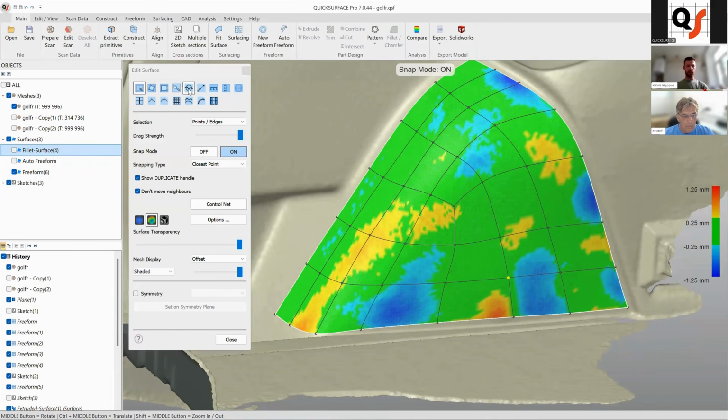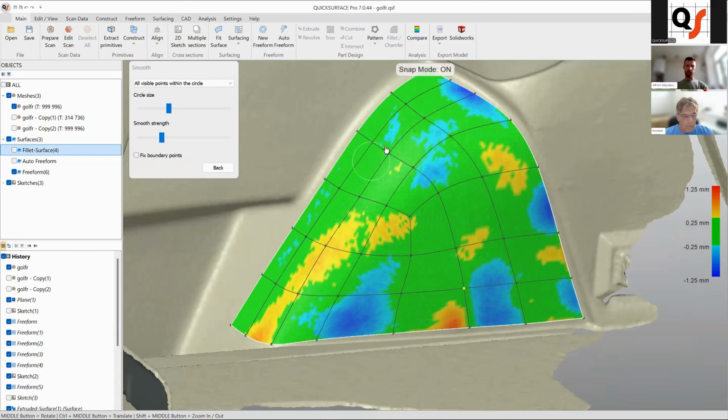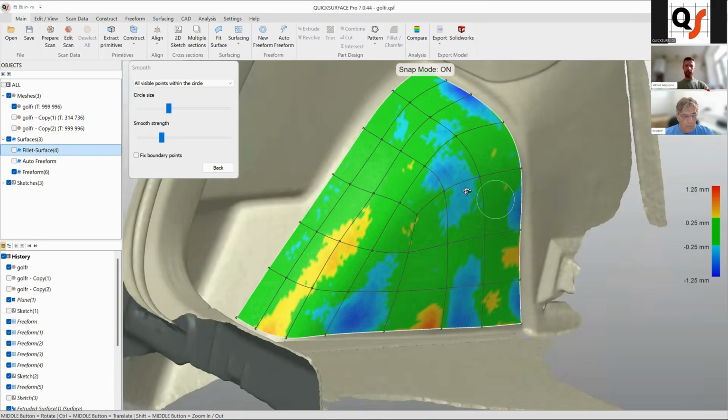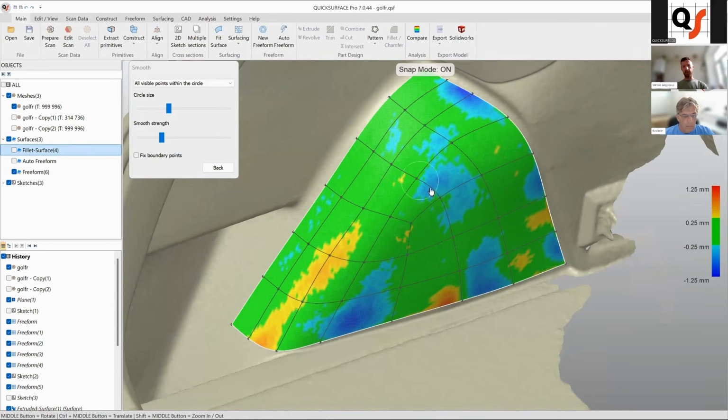this, and we have pretty nice tool, brush smooth. Basically what it does, it tries to make spacing between vertices more or less equal. So this way you will get even smoother results of your surface. But in some cases, it's not that useful when you have, let's say, transition of different surfaces. So sometimes you want to have different length of these edges or distance between vertices to get this transition more sharper, or smoother.